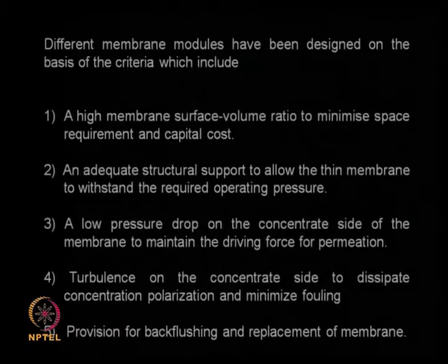I should also have the provision for replacement of the membrane, because you may be doing back flushing many times, but after some time the membrane has been fouled so much that there is no hope of recovering its performance, so we may have to replace the membrane. There have to be facilities for performing this type of job as well.